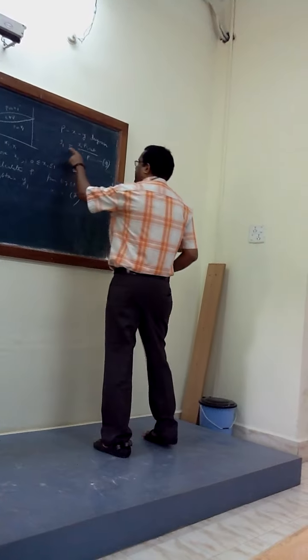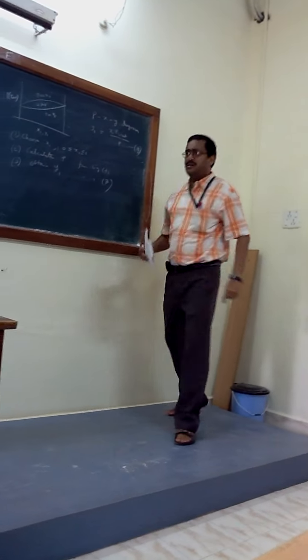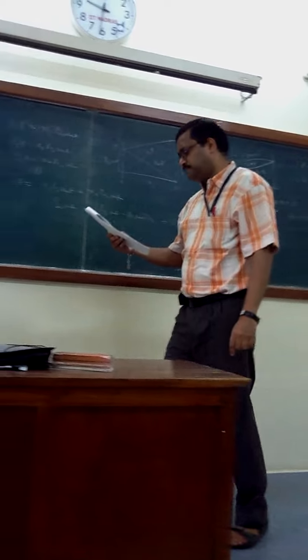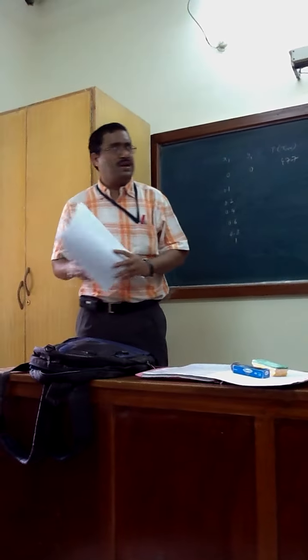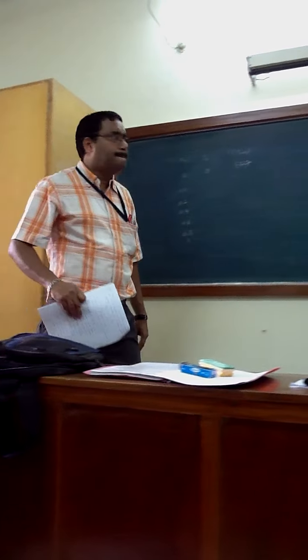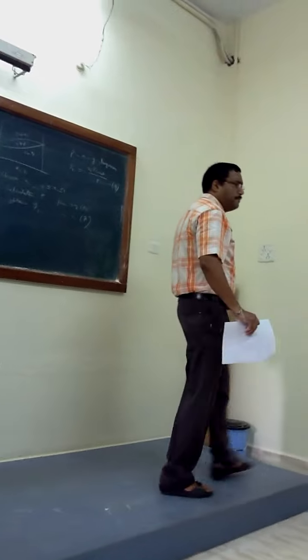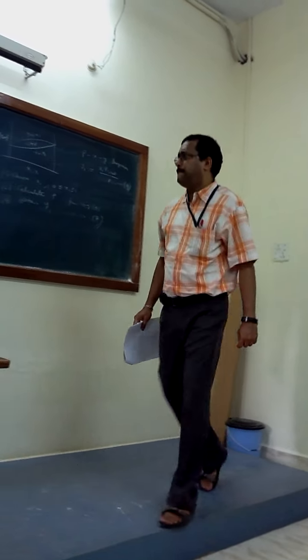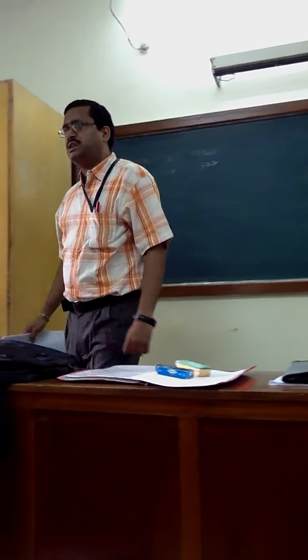If X1 is 0.1, then P1 sat is needed. P is how much? You know that. P is 760 torr. P1 sat you have to calculate. So make P1 sat, P2 sat handy. Keep it handy. Use the memory function.